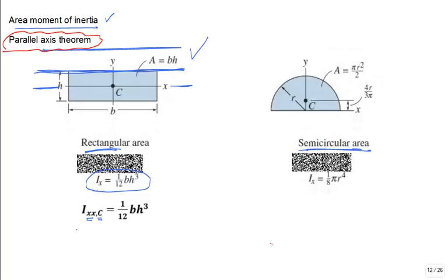All right, so some people had it. A lot of people wrote this. They say Ix through some other location. Let's say some location that goes through the point O. Put the point O right here. Some other location, or just Ixx, is equal to Ixx comma C. Are these the same? They look the same except for one little itsy-bitsy difference in the subscripting. What's the C meaning? It goes through the centroid. It's this one going through the centroid for that axis.